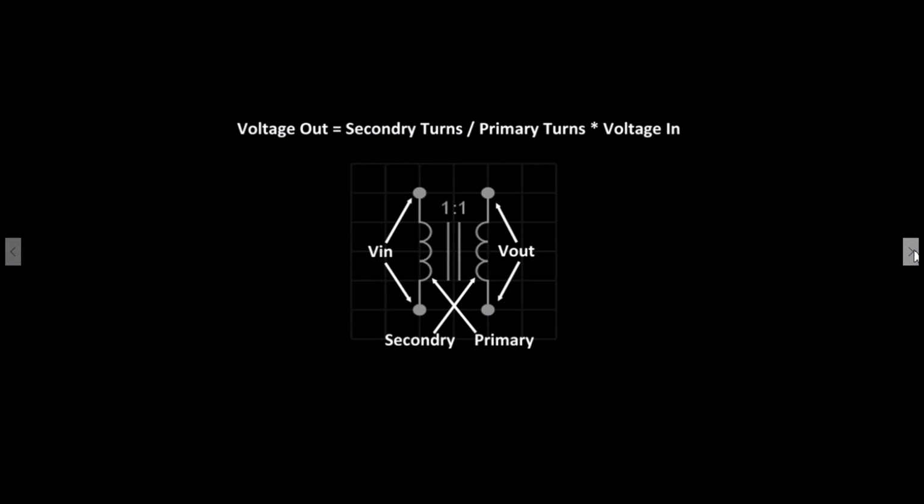When we go over to the simulator, we want to demonstrate how we can use the transformer to power an LED using a mains voltage supply. To do this, we must firstly make sure our ratio is correct to step down from 339 volts AC to 5 volts DC.